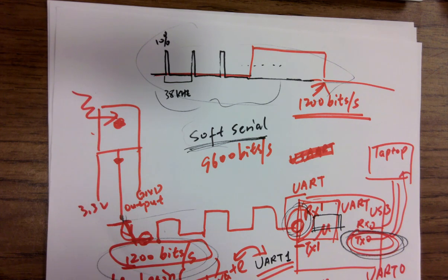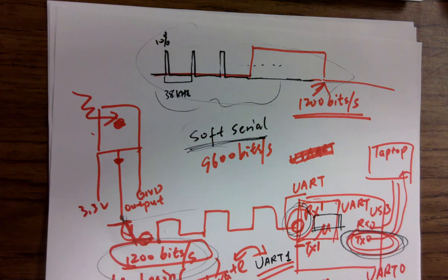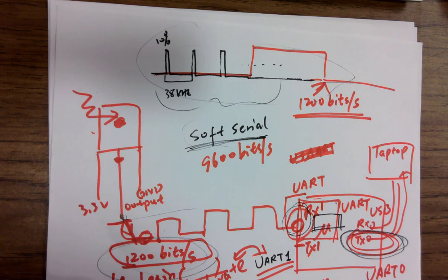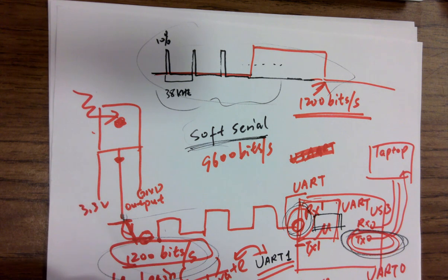What's next? It's the overflow. So it's going to be while it's not overflowing, semicolon. So wait there, and whenever the timer is up, it jumps out of the while loop, and then you clear the TOV3 bit by what? By writing a 1 to it. Remember the weird code? By writing 1 to it. Then turn off timer 3. How to turn it off? Give all zeros to TCCR3B, give a 0 to it.